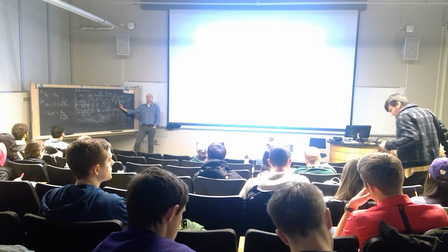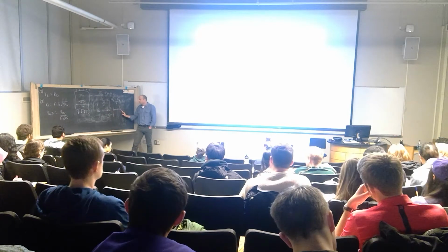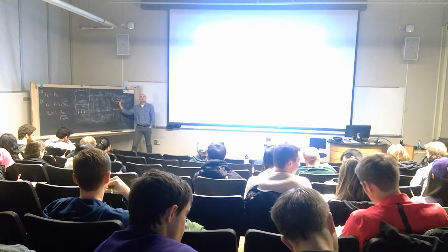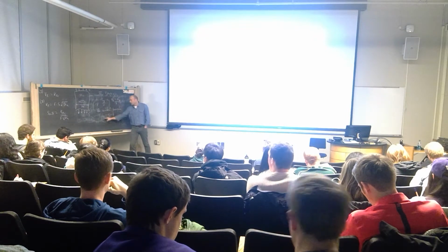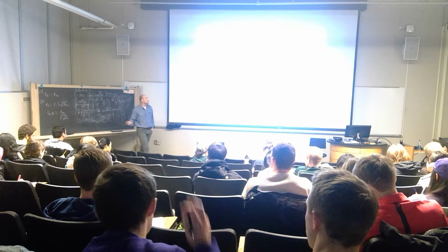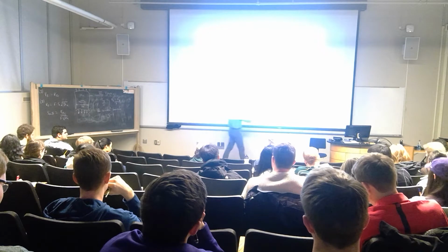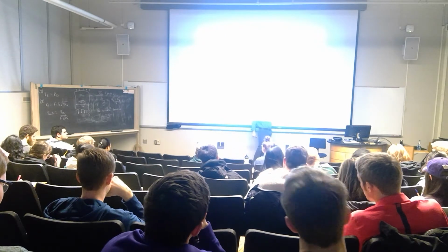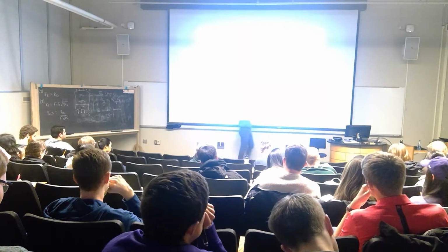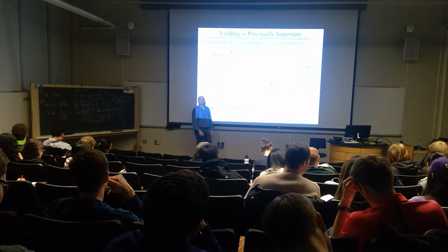So this is Tresca's failure criterion, which says that for uniaxial tension, failure will occur when the maximum normal stress, because sigma 3 is 0, this is uniaxial tension, is equal to the yield strength of the material. So any metal that has an ability to yield will yield first before it fails according to this criterion that we have associated with cracks, right? This is called the transition from linear elastic behavior to plastic behavior, yielding phenomena.